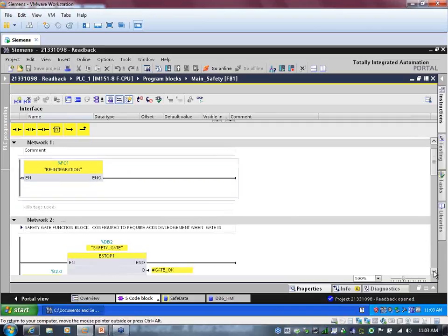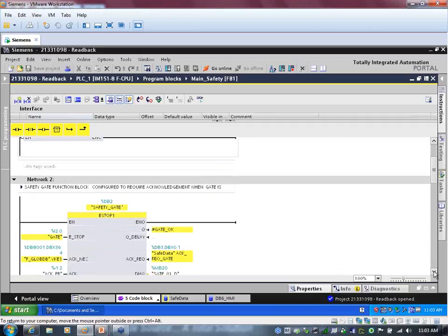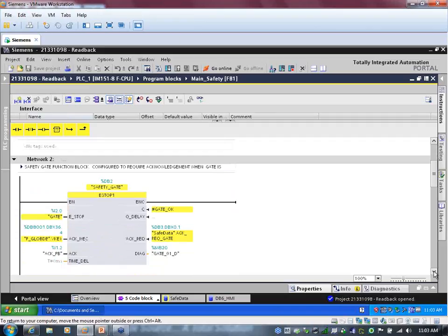So now we get into the actual code that I've written for my gate switches and my output module. In the configuration, we've chosen for the gate switches 2 normally closed contacts that are driven open. Think of them as operating essentially as an e-stop, normally closed contacts that I open. So I'm using an e-stop block.